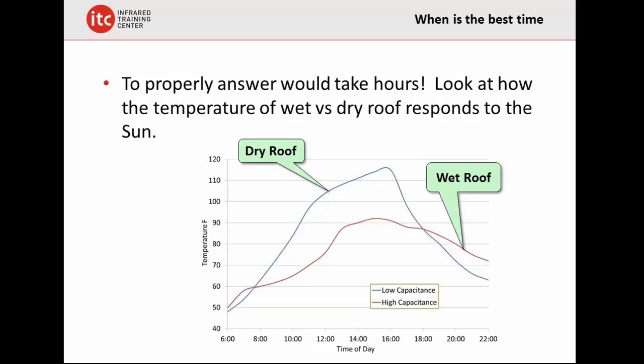Okay. So at some point in the afternoon, when the sun gets low on the horizon, it flips over. And then the wet insulation looks warmer because it has higher heat capacity, higher ability to store heat. And so this is the typical time that we go in there. This is what we call our roof window right here when it flips over. And this can stay for hours, or it can stay for 4, 5, 6 hours, or it can stay for a few hours.